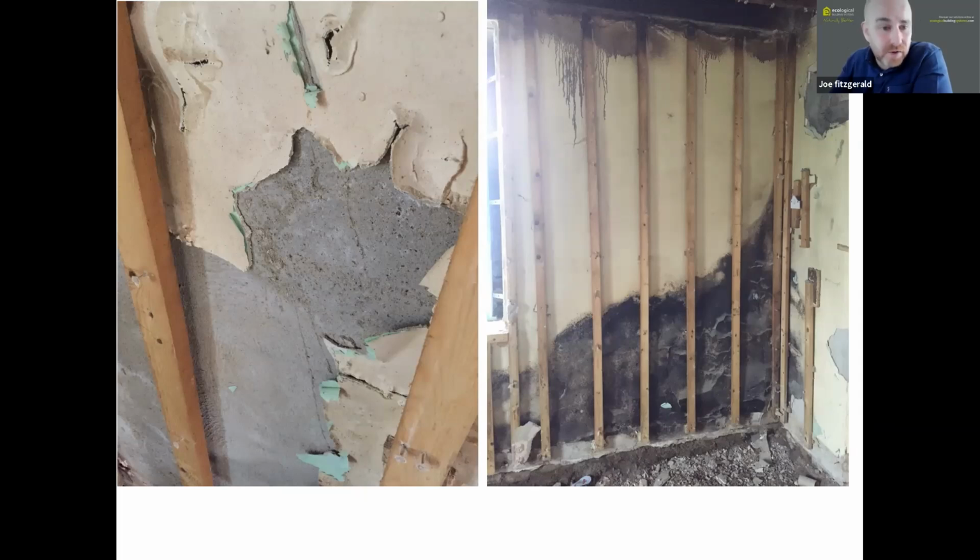And likewise, if you're going to build a dry line, you've got to consider that it must be well air sealed in the first place, because if not, warm, humid air will leak behind everything and get in there and get up to no good. So we'll look at dry lining a bit closer as we move on.